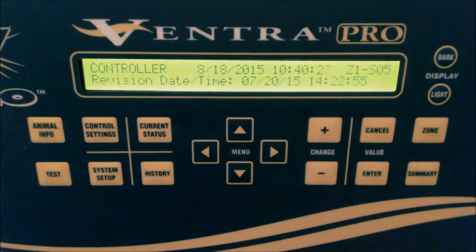This is usually due to external factors such as a motor not stopping instantly when the power is removed, or too much weight attached to the inlet machine, causing the motor to slip over time. This slipping can also be caused by the wind bouncing the device around. In addition to these hardware problems, the operator may move the device manually, then not return the device to the correct opening size according to the controller.